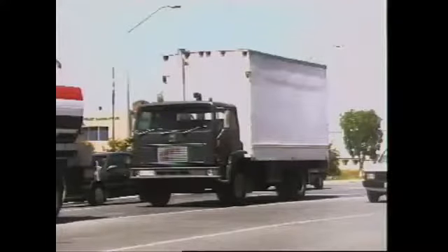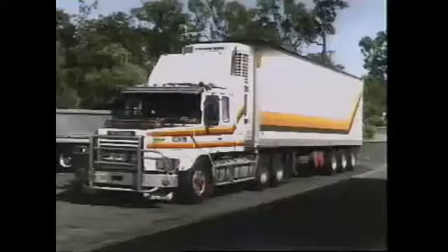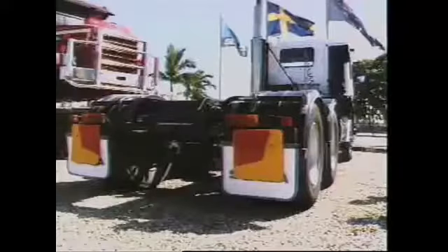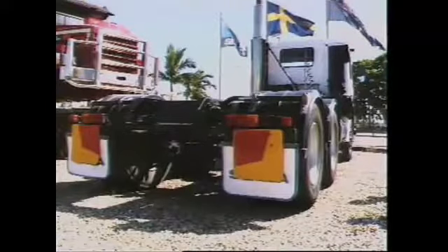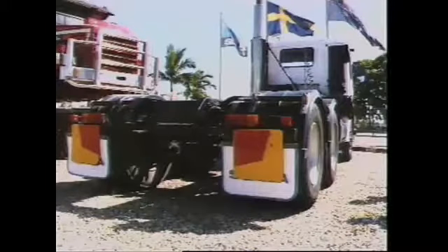On commercial vehicles, the load carried on a single axle is limited by law, so vehicles with extra axles are common. This layout has 6 wheels to support the vehicle, but only 2 drive it. The extra axle at the rear is only used to support the weight of the vehicle. This extra axle is sometimes called a lazy axle.